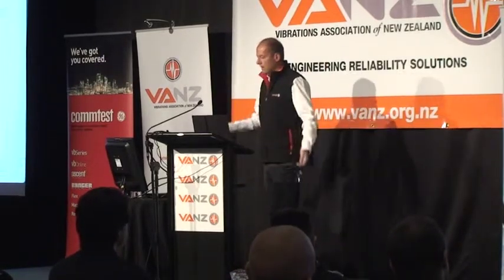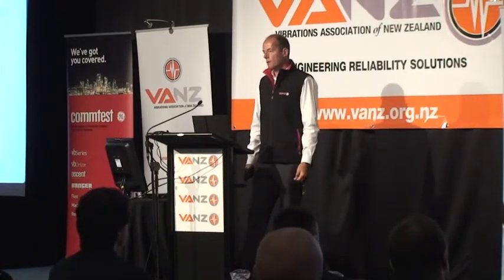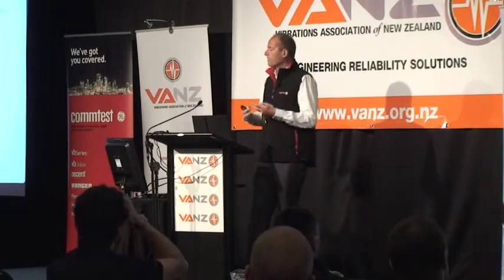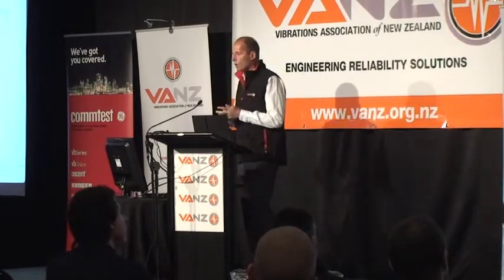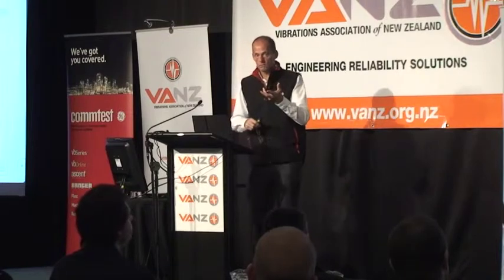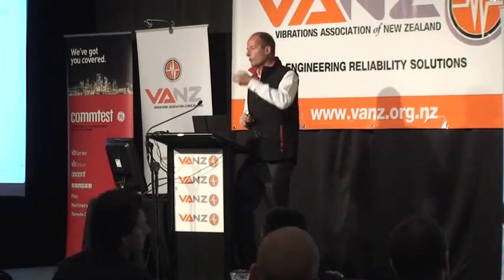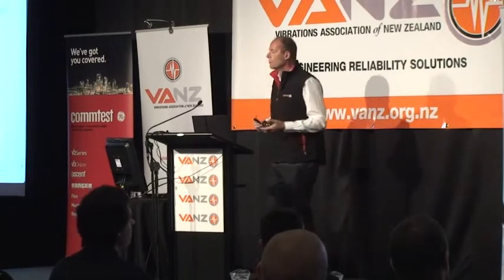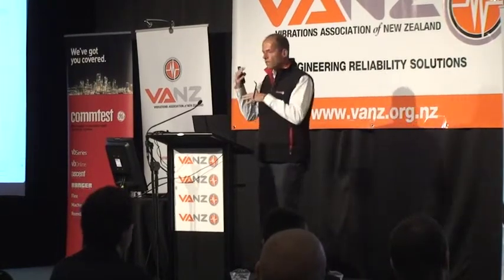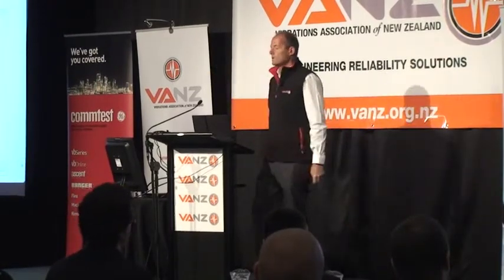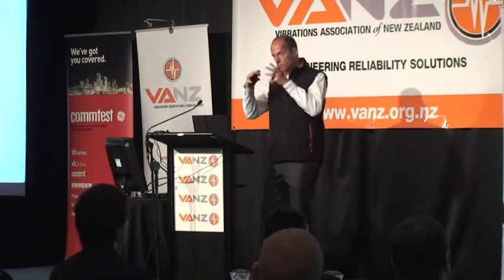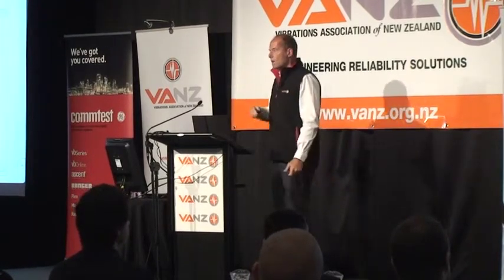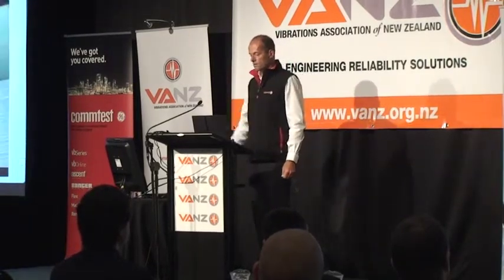Because if you think about it in terms of the bearing, that bearing, as I've mentioned, operates under tremendous strain. It's designed to manage it, but once you overload it with unbalance or resonance or misalignment, or you don't lubricate it properly, then it fatigues, and it might fatigue down, subsurface at first and break through to the surface. But all of those issues cause these bearings to fail.